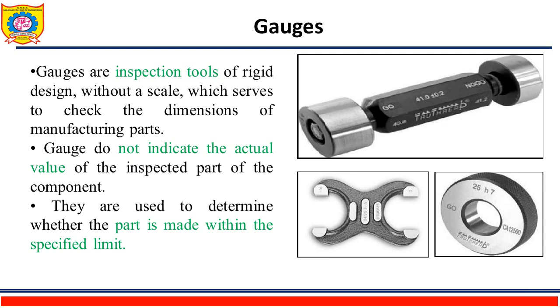We know that with the help of measuring instruments, that is the conventional measurement process, it is difficult to measure each and every dimension of the given component. But with the help of limit gauges, measurement is faster, easier, and does not require a skilled operator.